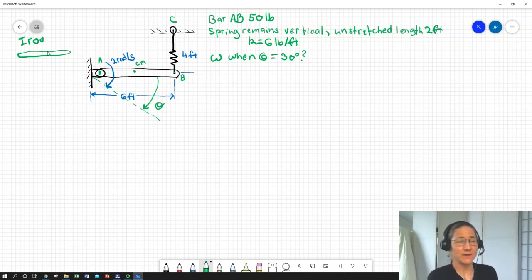You can also look this up on the internet or in any kind of reliable handbook. If we look at the moment of inertia of a slender rod about its center of mass, we find that it's 1/12 the mass of the rod times the entire length of the rod squared. But about the end, it's much bigger. It's 1/3 ml squared.